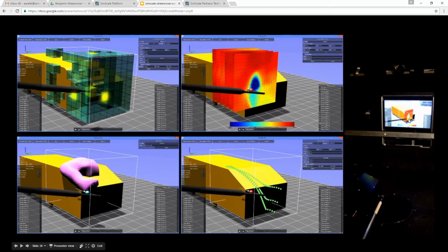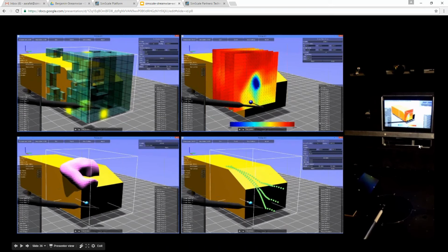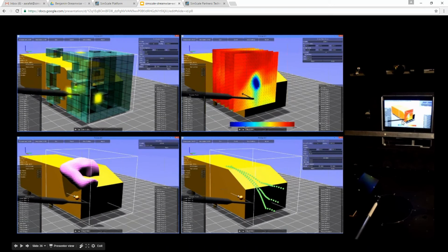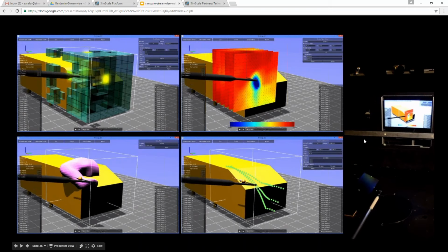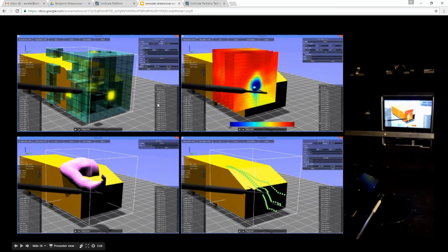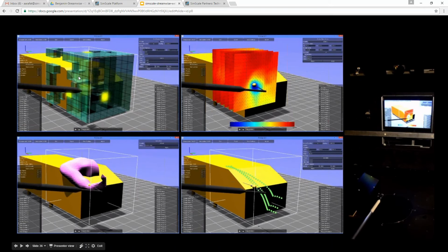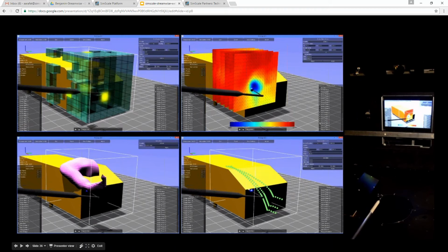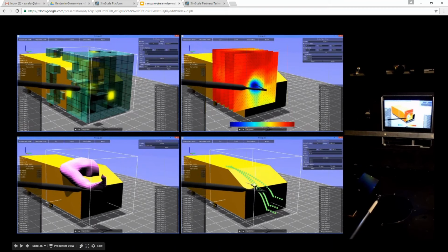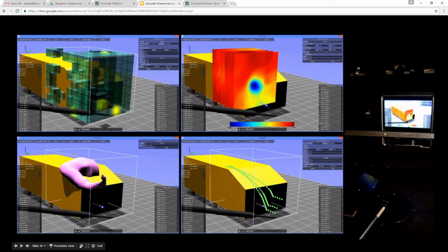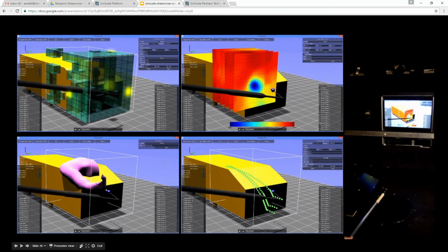Then on the right hand side of the movie you see the screen that the operator sees in the wind tunnel. So this is the live feedback he can see during measurement. And the big 4 screens you see are just alternative screens you can also see. So you have the option of the voxel eating on the upper left corner. So the probe goes through the measurement volume and eats away the voxels, and so tells the operator where the data density is already high enough.